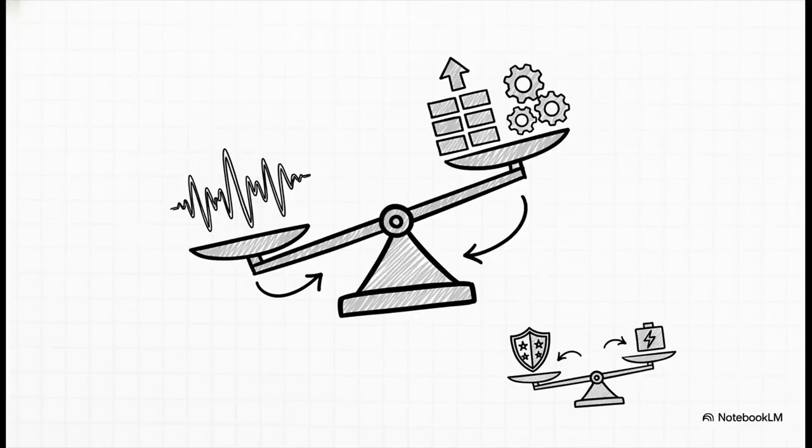And this, right here, is probably the most important lesson I can give you today. From your sampling rate, to how many quantization bits you use, to the line code you pick, every single decision is a trade-off. You want higher fidelity? It's going to cost you more bandwidth. You need to save battery power on a device? Well, that probably means a simpler system that might be less robust to noise. A systems engineer lives in this space, constantly balancing these competing demands.